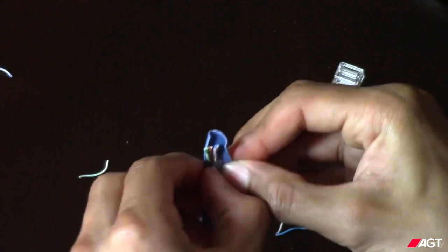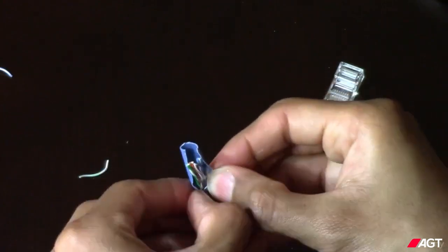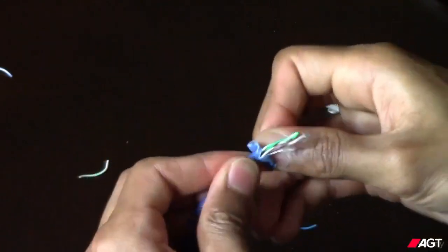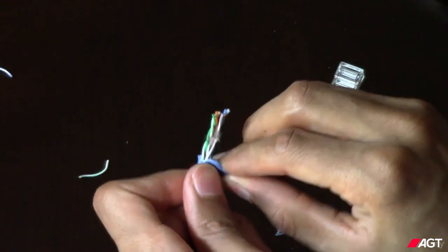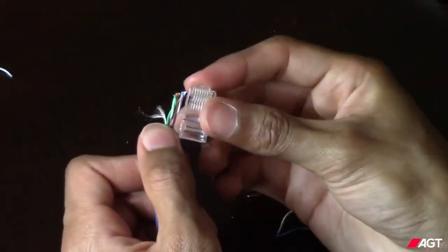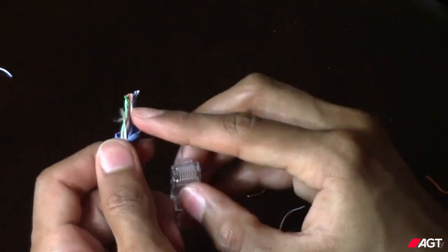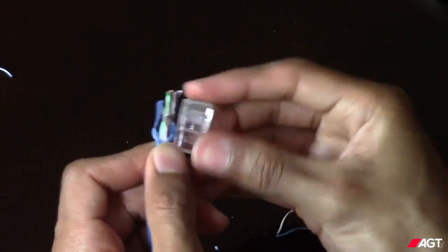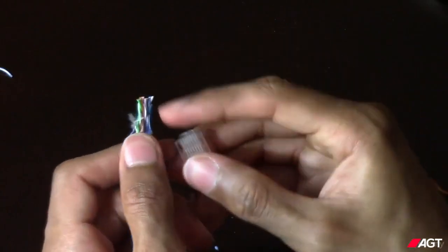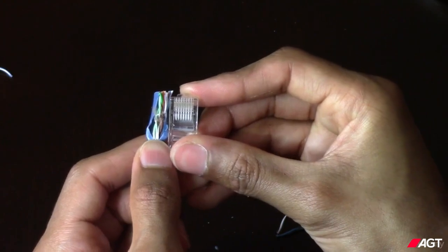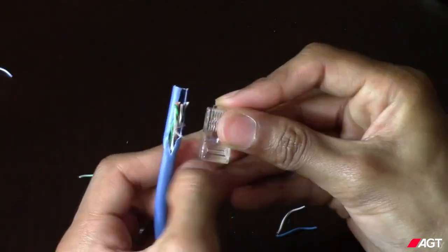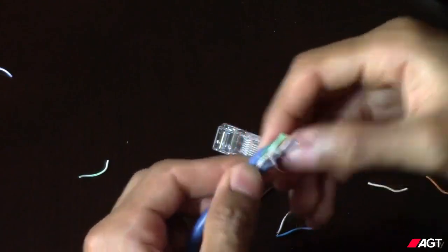Slowly open up the sheath a little more using your hands. Now you can use the connector to measure where the sheath should end. You're eventually going to want to cut off a few millimeters of wiring to make sure that they're even at the top, and we'll be using a crimper to do that in just a minute. Remember, you don't want any exposed wire between the sheath and the connector. Once you've measured the length of the sheath and determined where it should stop, go ahead and cut it off.